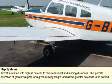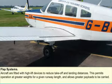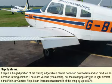Aircraft are fitted with high-lift devices to reduce the take-off and landing distances. This permits operation at greater weights from given runway lengths and enables greater payloads to be carried. A flap is a hinged portion of the trailing edge which can be deflected downwards and so produce an increase of camber. There are various types of flap design which all increase both lift and drag in varying amounts.